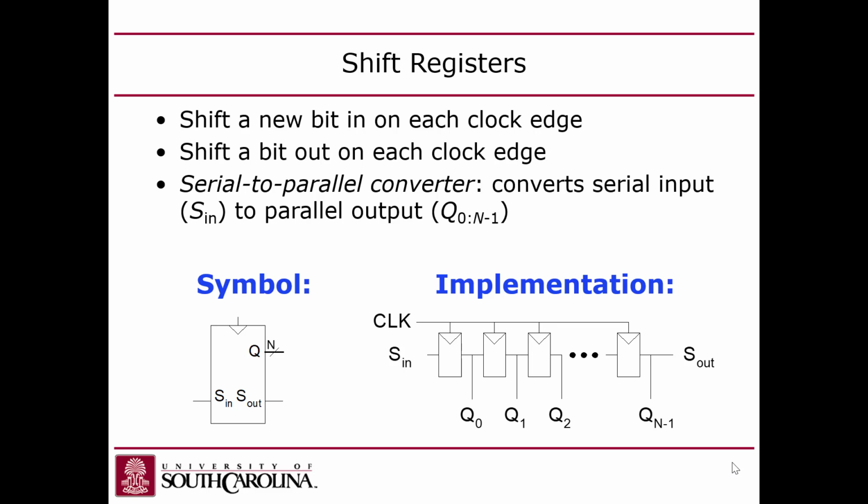Well, sorry, I take that back. The rise time is not relative to the clock period, but usually you see it about 1/10. But if you were to extend the clock period, the rise time wouldn't extend with it proportionally, right? So if the rise time was a gradual slope versus just like a cliff jumping straight up, then you could have issues. Yeah, you would end up violating timing.